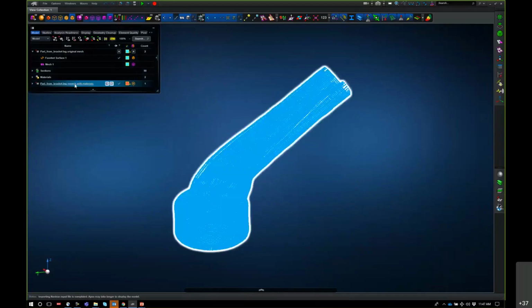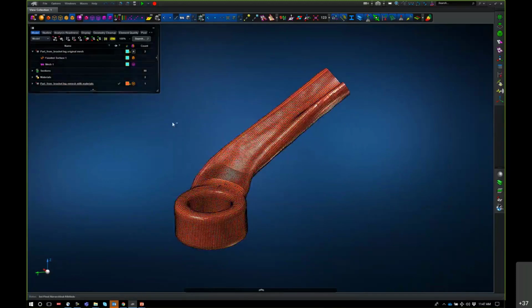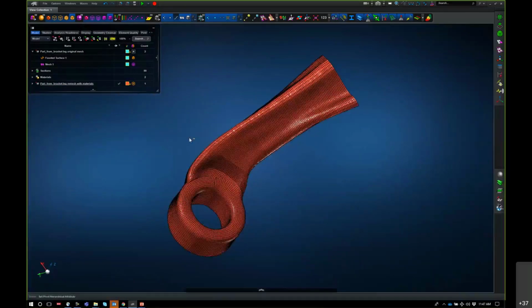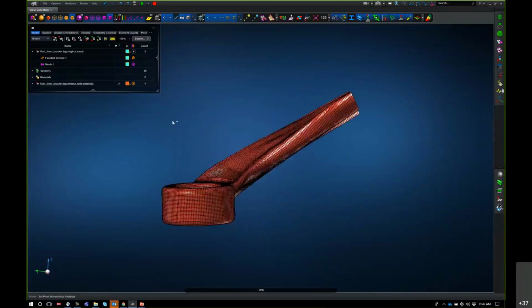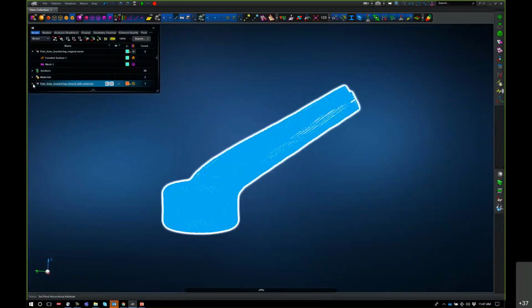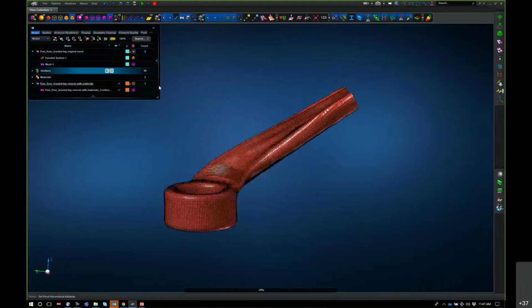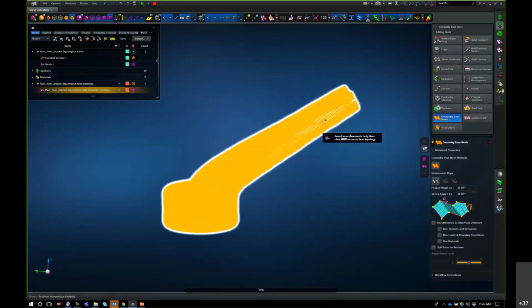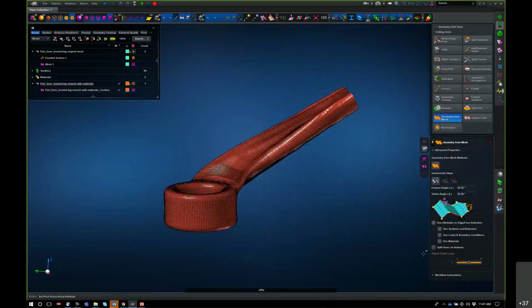So I have this new model now, mesh, and I use a fine mesh. I learned that's probably not the best thing to do. All it is is the mesh and a bunch of sections. So I come back into the tool. Now this is an orphan mesh. Now I'm going to use these attributes. I'm not going to split up on the features and find faces. I'm going to use these attributes literally. In specific, I'm using the sections.